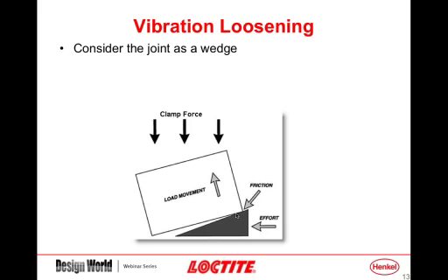And typically when you tighten up a fastener, and I'll use a half-inch fastener as an example, when you've tightened a half-inch fastener to its recommended torque, you're generating on the order of 5,000 to 12,000 pounds of clamp force on that. So that's holding these two surfaces together and obviously your fastener together. But if you go to disassemble a nut and a bolt, it typically takes about 70% of your tightening torque to start a fastener to loosen again.